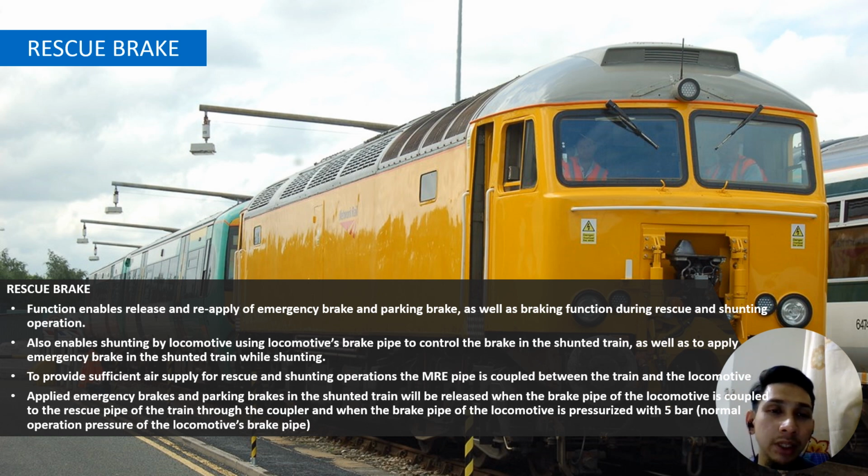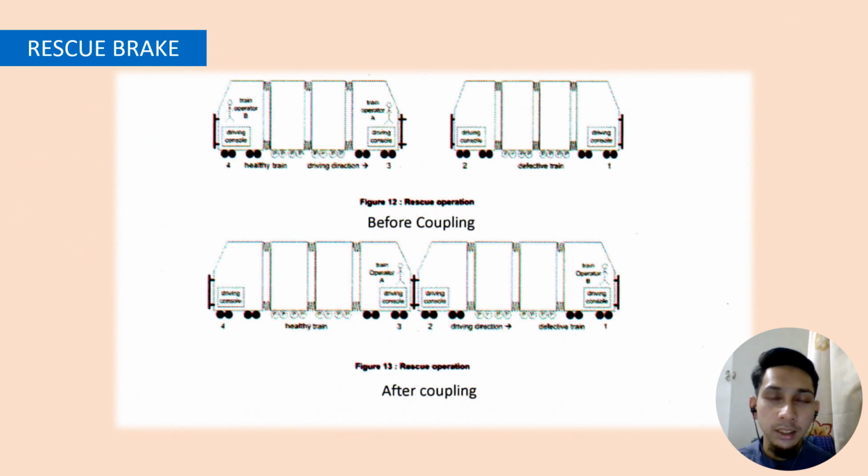Applied emergency brake and parking brake in the shunted train will be released when the brake pipe of the locomotive is coupled to the rescue pipe of the train through the coupler, and when the brake pipe of the locomotive is pressurised with 5 bar, which is the normal operation pressure of the locomotive brake pipe. In this slide, you can see the rescue brake before coupling and the coupling, which is the rescue operation. So after coupling, the rescue train will control the brake system of the shunted train.